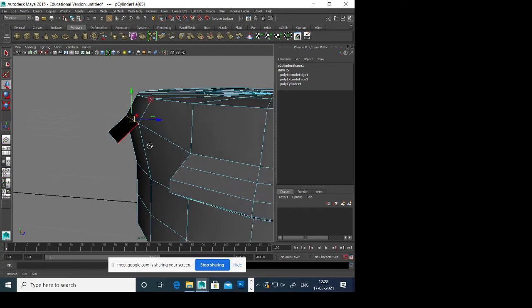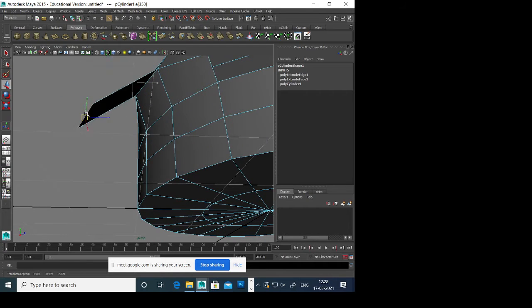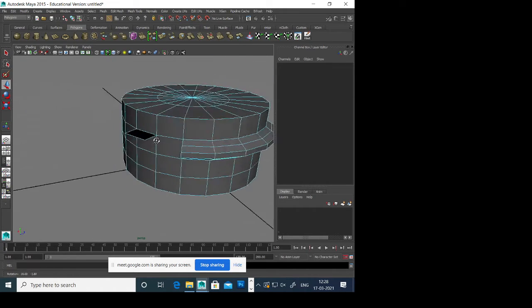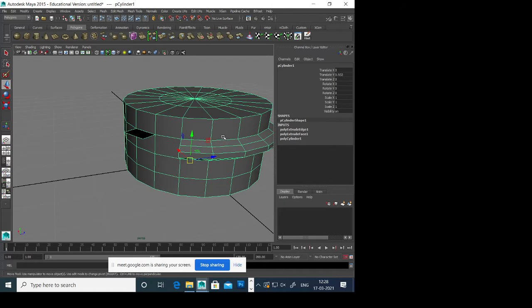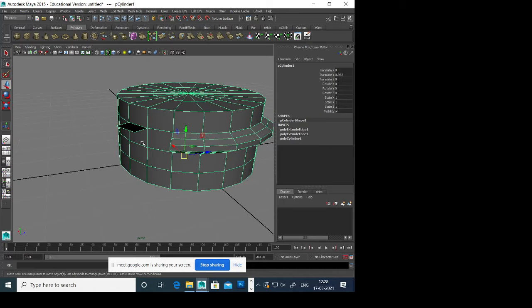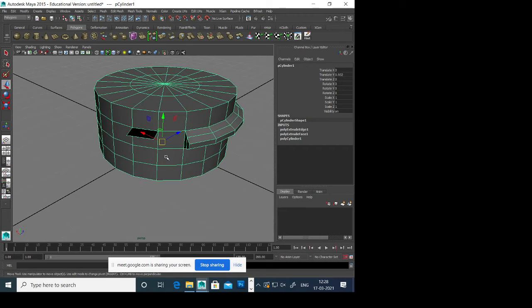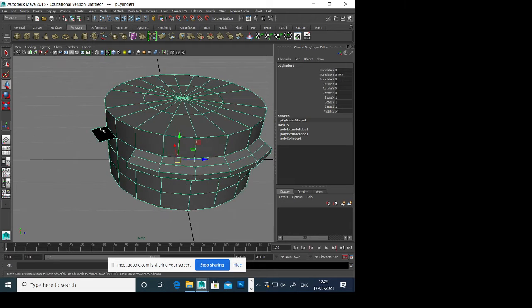Edge. You see, just the edge extruded. Okay, extruded, but this is wrong geometry. This is not allowed. But there's one more very handy thing. Suppose you have wrong geometry in your model, of this kind. This is called non-manifold geometry, right? So this geometry is not acceptable. So how to fix it? Suppose it's a huge scene and you need to fix this. In that case, it will become very difficult to search for it and fix it.